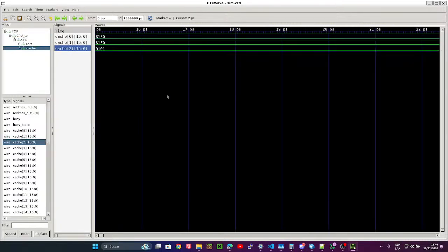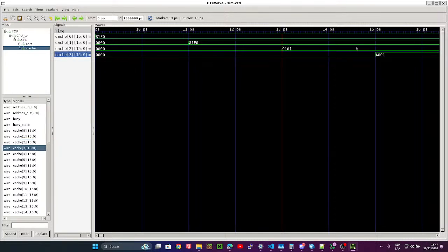So you can see when I go here, the same instruction is repeated here and here, and then the next instruction is here, and that's not supposed to happen. Suppose this one should be load immediate. Then this one is add immediate, which will be this one. The next one is hold. And it's not working properly. It looks like it's just off by one. Yeah, off by one, and repeated here. Infamous error.